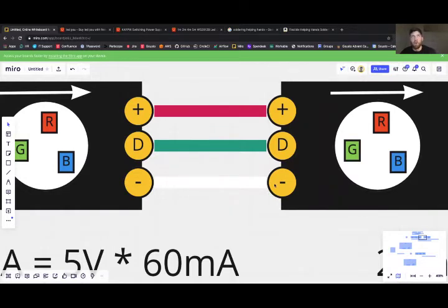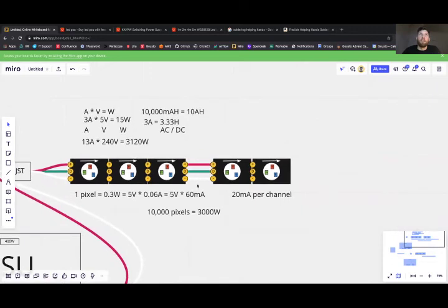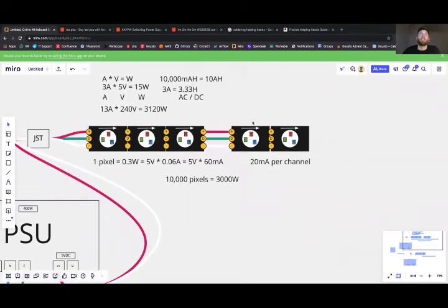Now, I have discovered over time that the best methodology for doing this is actually to place the tip of the soldering iron underneath the pad and then hold the solder spool on top of the pad. And the soldering iron will heat up the pad from beneath and make the pad itself hot enough to melt the solder spool, which will then bead up onto this copper pad and eventually melt. So that is the pro tip for soldering LEDs together. Most of your soldering can be avoided with good project design.